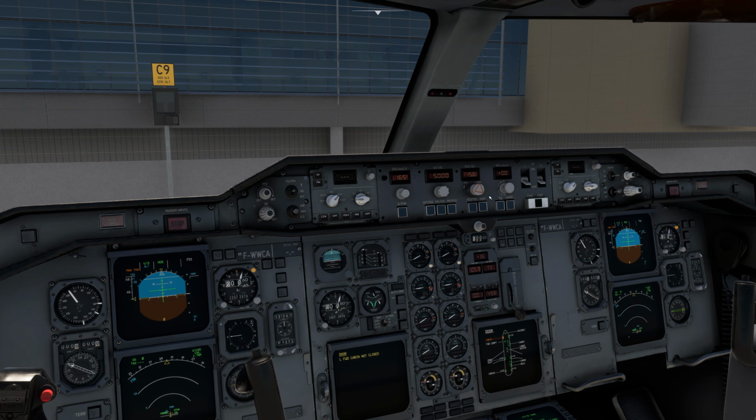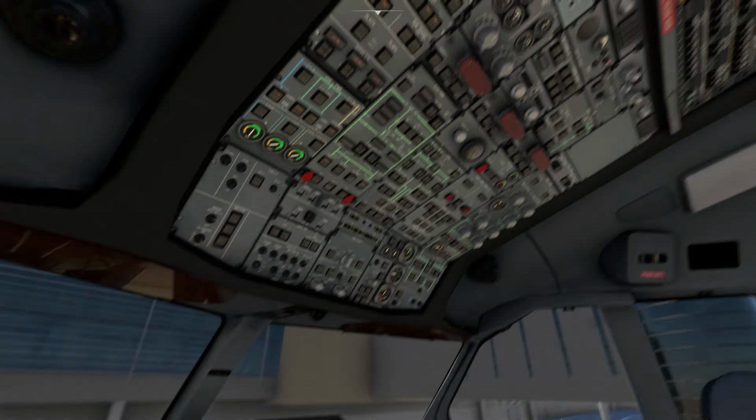But in some cases, if you're communicating with the ATC, they might give you a heading. If you're using VATSIM, then instead of flying in the nav mode, you fly in the heading mode. In this video, I will not tell you how to, or maybe I can just give you a little bit of introduction on how to fly in the heading mode. But for this video, I will stick to nav. Now you have configured the FCU and everything is done. It's time to lock the cockpit doors and start the APU.